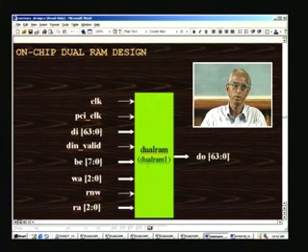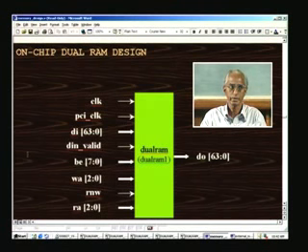mode or read mode. Out of the 2 RAMs, say RAM 1 and RAM 2, only one RAM will be in write mode, the other will be in read mode. That is how we accomplish a continuous stream of image being fed in. So processing is happening concurrently, and in order to distinguish this, you have another control called RNW, N for negative, that is, read is low, and write is high.